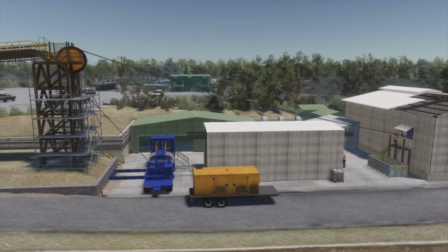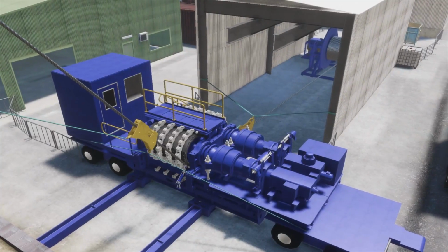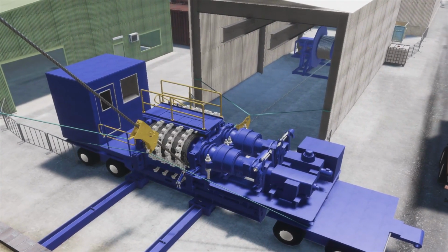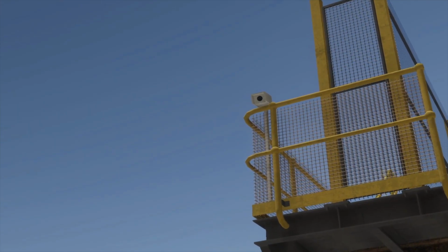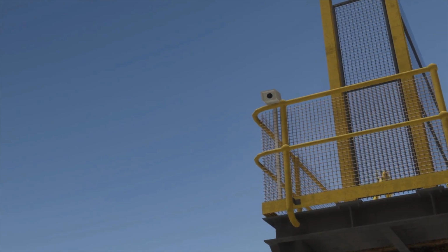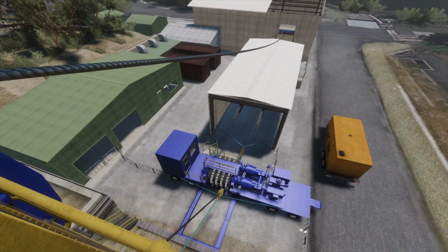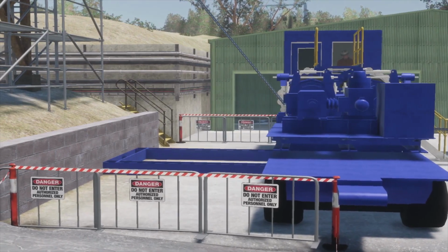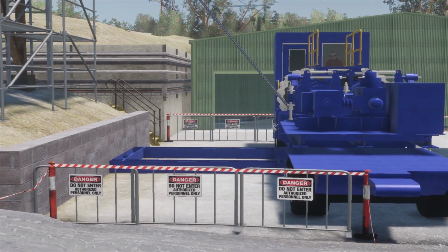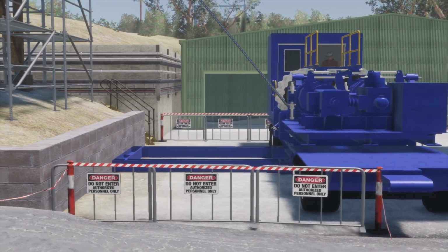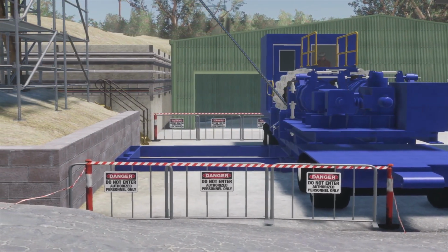The rope removal methodology lacked engineering controls to prevent the rope becoming over-tensioned, had no method of obtaining information in real time of the actual line pull forces being exerted, and had no method of remote task observation, such as cameras, eliminating the need for workers to be positioned within hazardous areas. The rope removal procedure did not incorporate higher-order controls, such as hard barricading, to create a physical barrier to hazardous areas in the potential drop zone of falling objects.